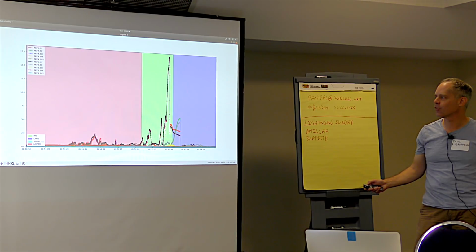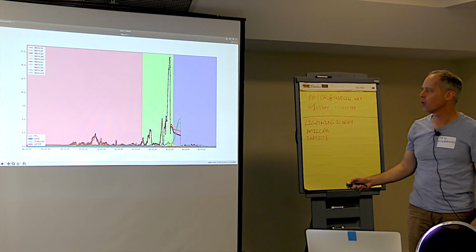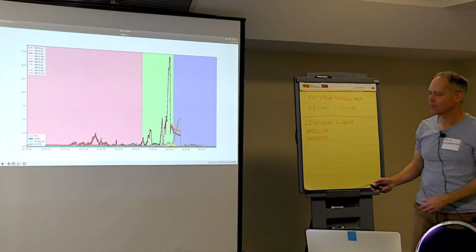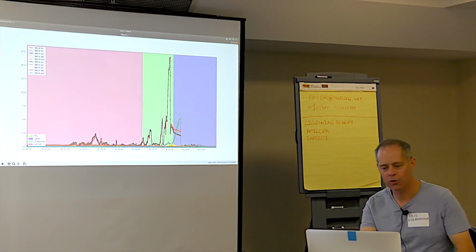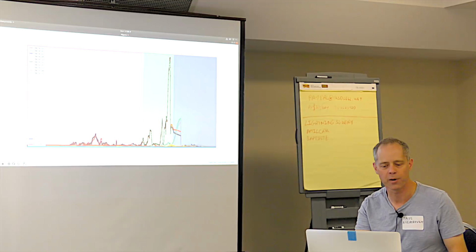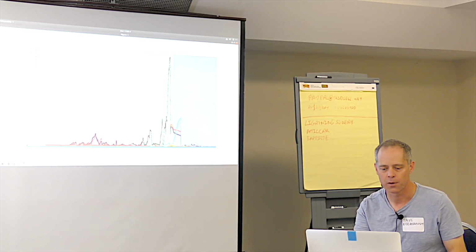Here we see evidence that these normalized innovations have gone above 1, and I go, well, that's interesting. So straight away they're above 1. That should have been a red light or a red event on the ground station. And normally, as an operator, if you saw that, that really should trigger the question, do you want to RTL?